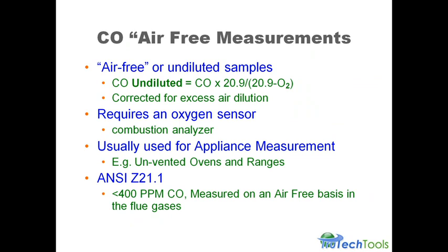They sell them because people buy them, and they do exactly what they say they'll do, but people don't know what the standard is or how to meet it. So I'm telling you right now, if you're using that type of appliance, you can't do the testing that's outlined in the standards, and you need to get a combustion analyzer.